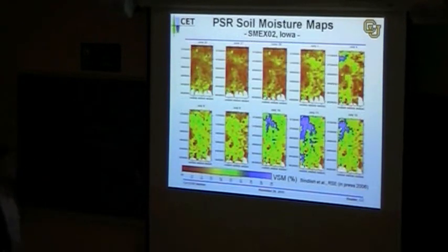What do we get out of them? Well, here's some imagery of soil moisture. Now, let me spend about 1 minute talking about how we got this imagery. We took our aircraft and we flew back and forth, and you can see the edges of these scans here. As we flew along, we operated in conical imaging mode. So the beams of the radiometer were moving across the ground in a stretched corkscrew fashion. And we were sampling and scanning fast enough that we essentially had those beams overlapping by around their 3 dB width or so, give or take. It was almost Nyquist sampling, not quite.